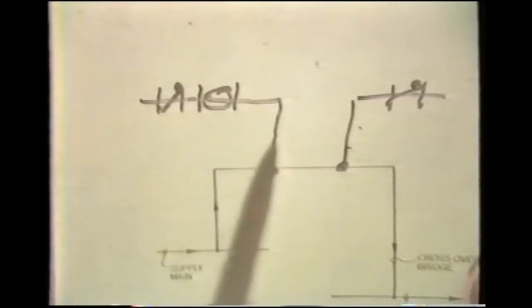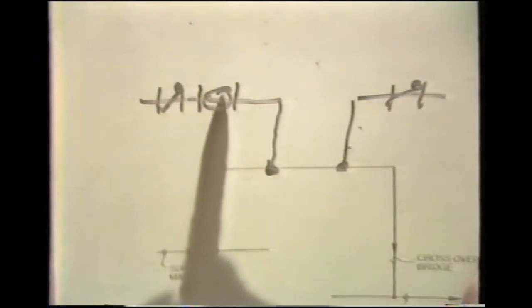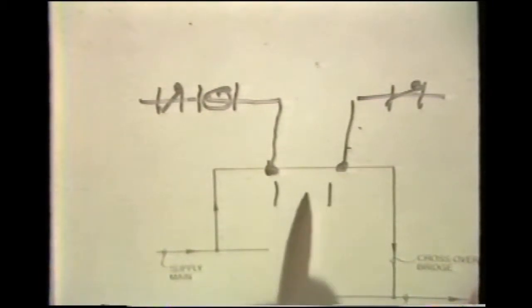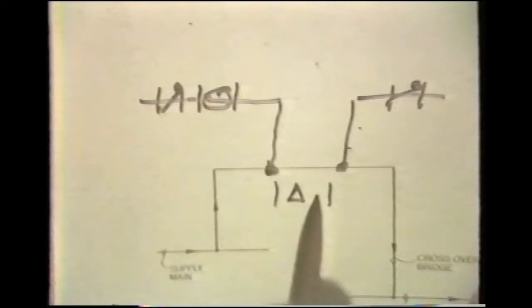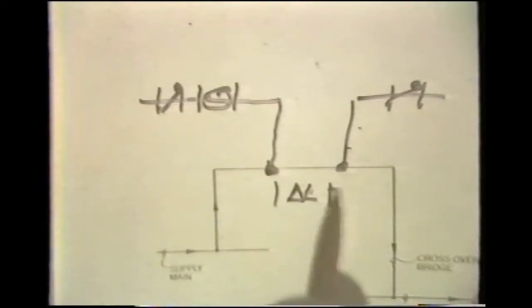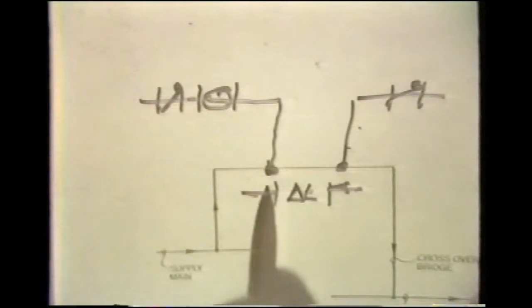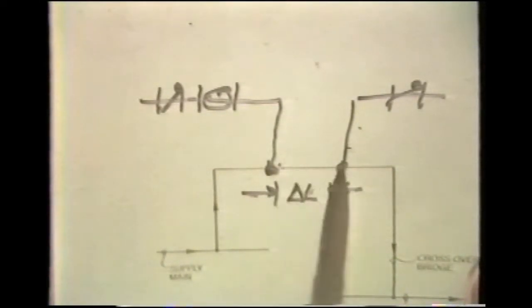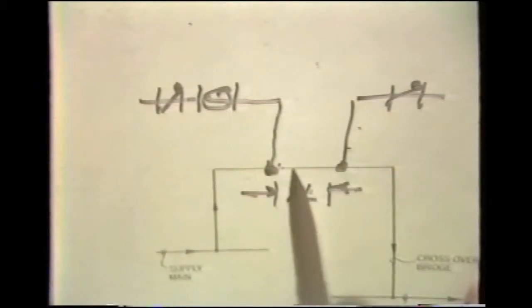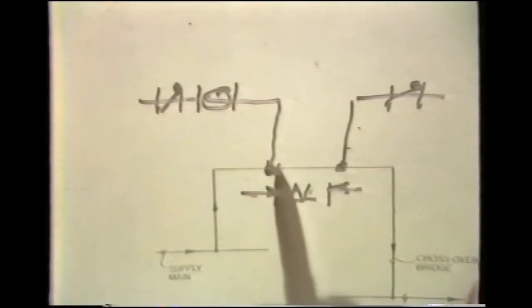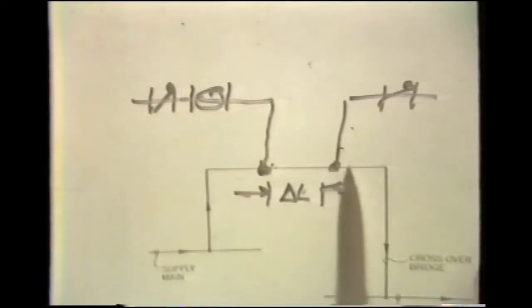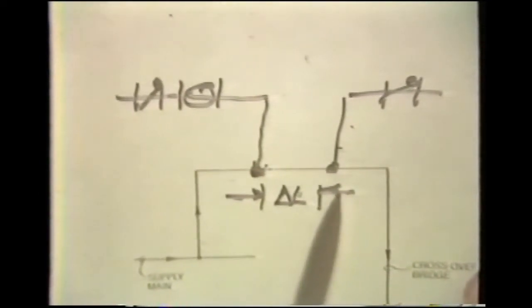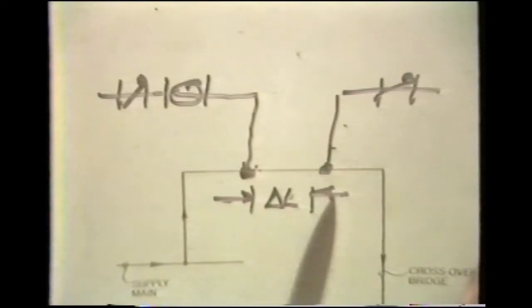Because of the necessity for completely stopping flow when the pump stops, the difference in terms of length for this application means that the T's should be placed fairly close together and the common piping length should be relatively short. On the other hand, for most applications involving primary-secondary pumping,